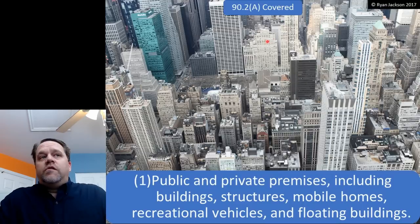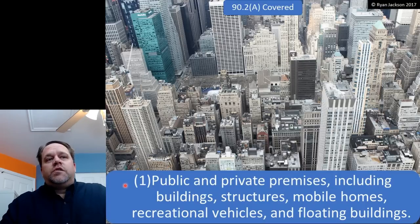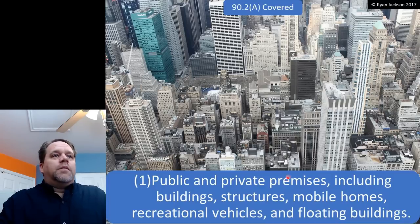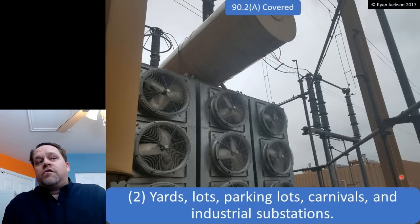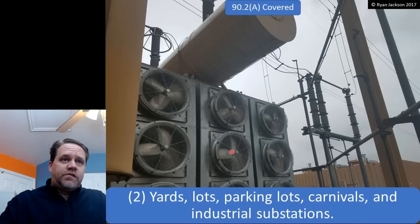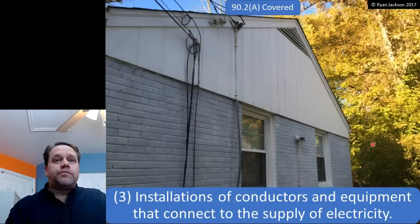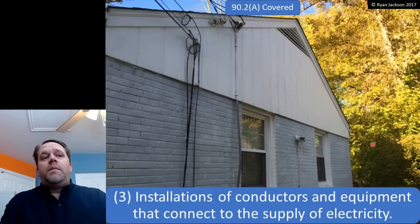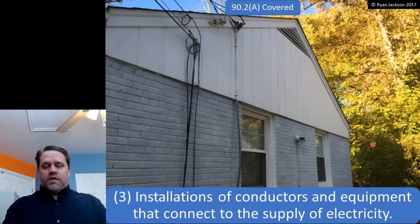So 90.2(A), what's covered? Installations of conductors and equipment in public and private premises, including buildings, structures, mobile homes, recreational vehicles, floating buildings. So everything you can see in this photograph here is probably covered by the NEC. Code covers yards, lots, parking lots, carnivals, industrial substations. This stuff is covered by the NEC, unless 90.2(B) says it's not. Installations of conductors and equipment that connect to the supply of electricity. Again, the code covers everything that's installed, unless 90.2(B) says it doesn't.